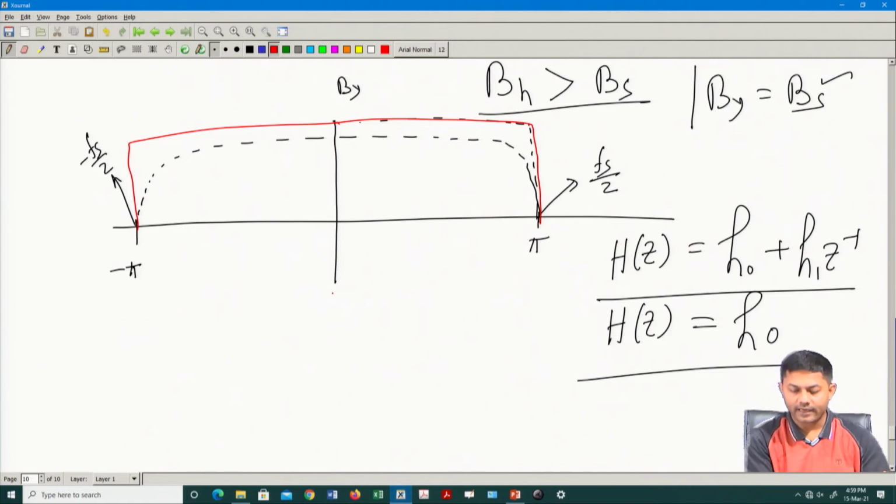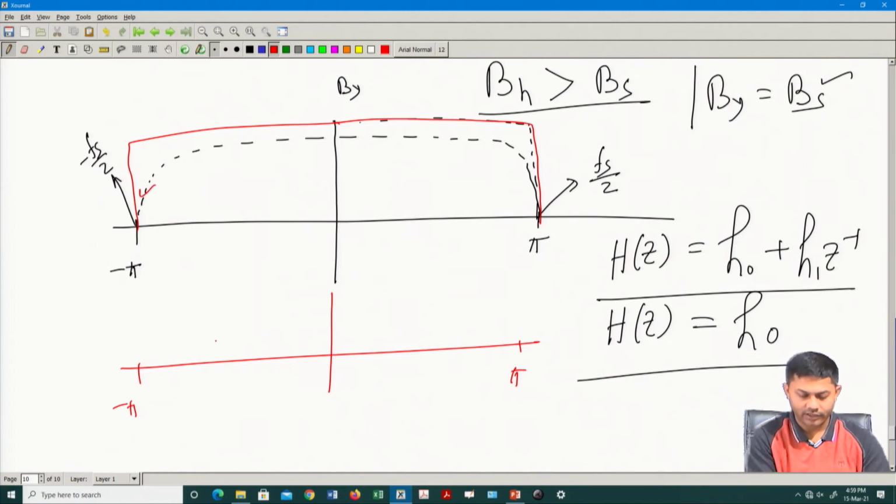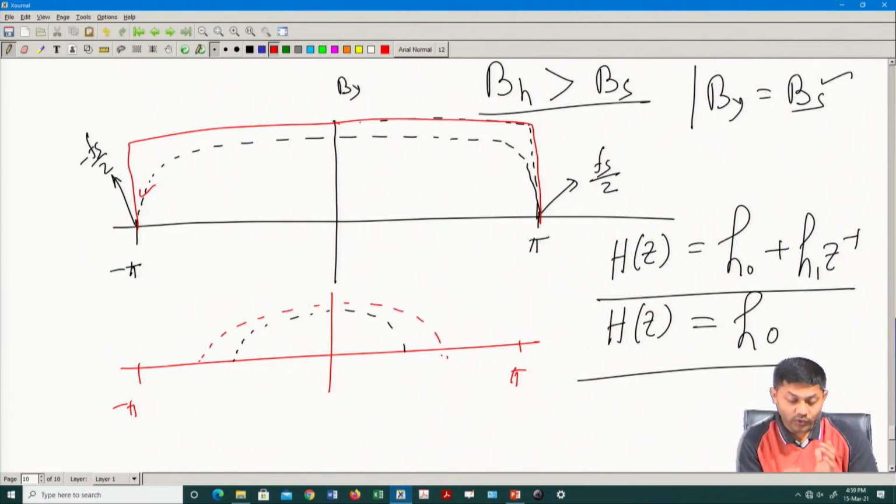Or it can happen that I am sampling at a higher rate, so that I can view the data. So, this data is dotted data, this is my higher sampling rate, my channel bandwidth is larger to it. So, with respect to my transmission window, if I do not look at anything beyond my transmission window, what does it mean?